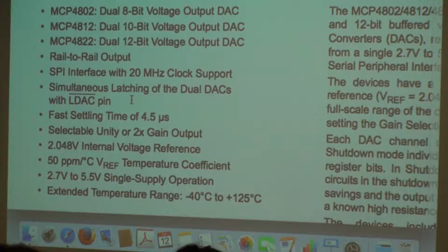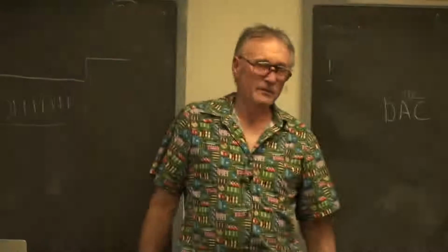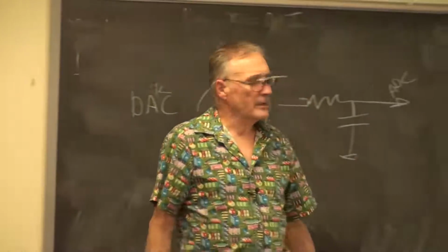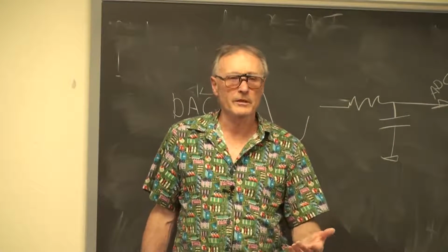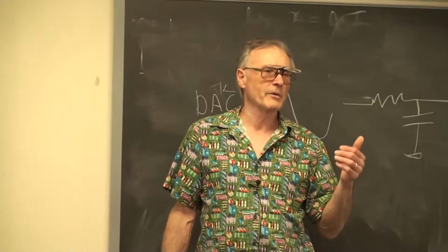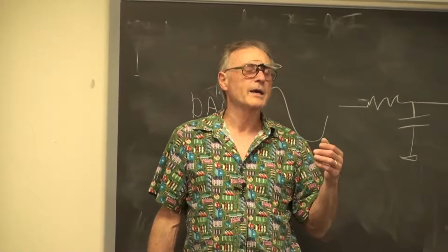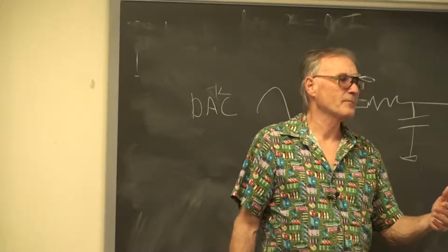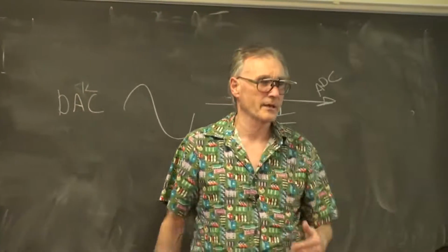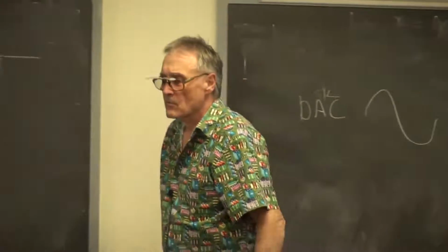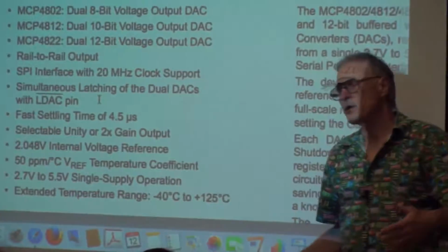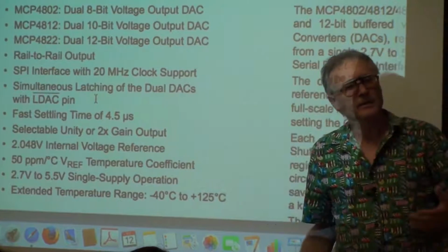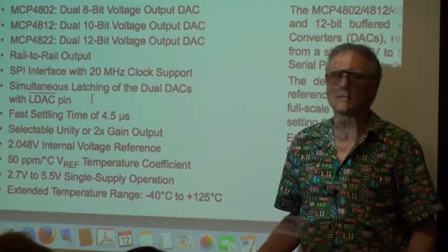However, if you want to go for very high frequency synthesis, let's say you want to generate a radio signal, then you can use an external parallel DAC. I'm not suggesting it for this lab. You can use an external parallel DAC and feed it with DDS samples by direct memory access. And then you can get 3,200,000 samples a second. I would say for this lab, you're going to want to be in the region of 8 or 16 kilosamples a second.